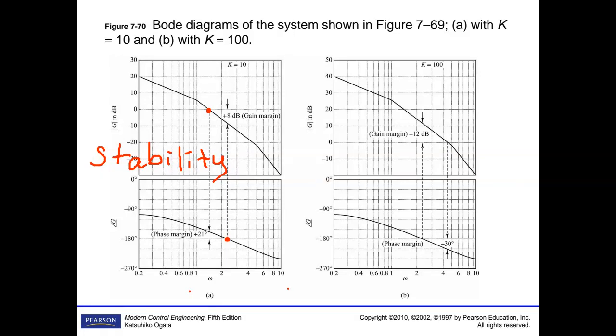Now, if you look at those curves, you are going to obtain where your gain function is crossing zero. As long as you obtain that point, you come to the angle curve and you obtain the point how far it is from 180 degree.